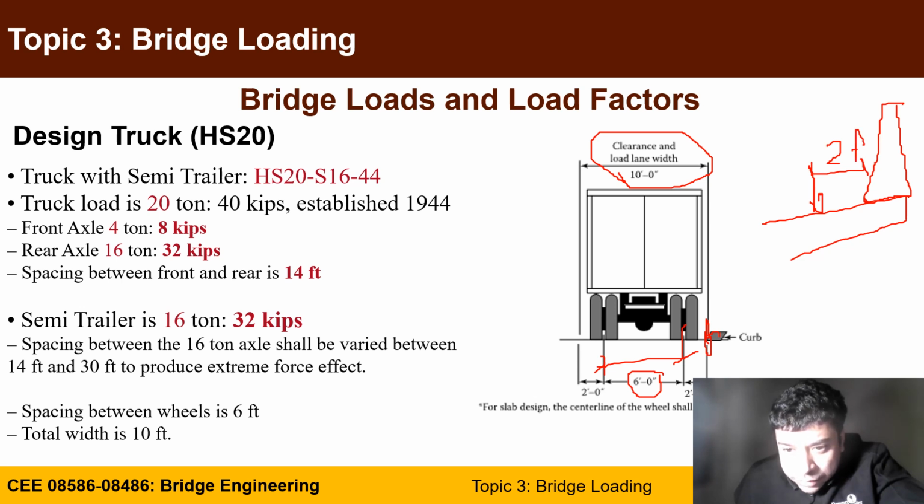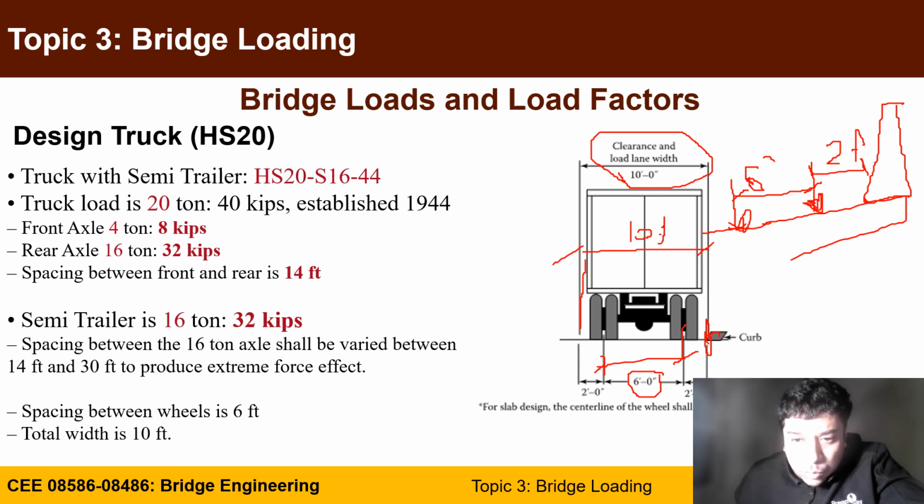You put your first load in the transverse direction, and at 6 feet you put your second one, and you end up with the end of your truck. Remember, the truck is 10 feet, but the design lane is 12. We will show how we have to lay out the trucks later on.